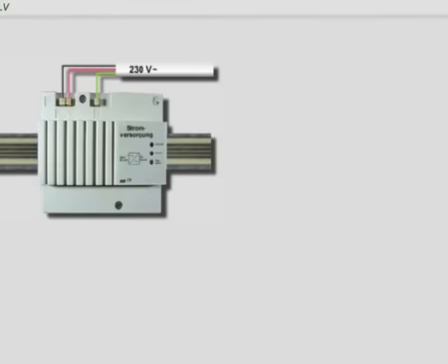The power supply unit has to be earthed via a green-yellow coloured conductor. Static charges of the bus cable can then be avoided.